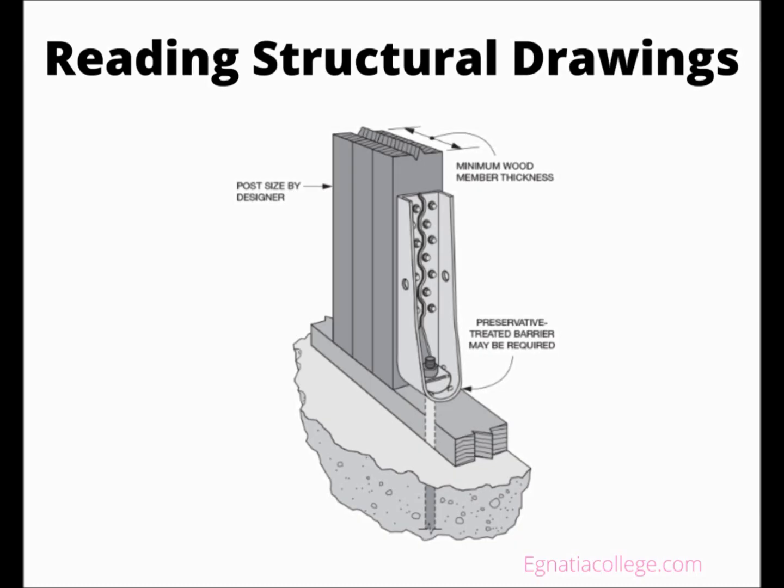One end of the tensioning cable is then anchored and a hydraulic tensioner is used to stretch the cable inside the slab. The plastic coating allows the cable to stretch inside the now solid concrete. The cables are tensioned to approximately 33,000 pounds. Specifications for the spacing and how much the cable will be elongated once tensioned are shown on Urban Quartz Sheet S7.1. Post-tensioning is similar to pre-stressed concrete beams used in highway bridges, and the result is the same. The cables are pulling the sides of the concrete slab together, and the slab gains a much higher resistance to tension stresses.